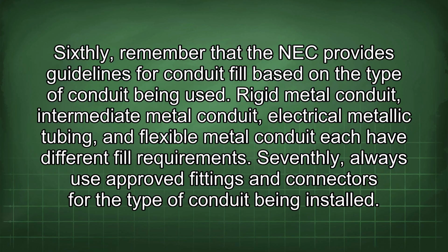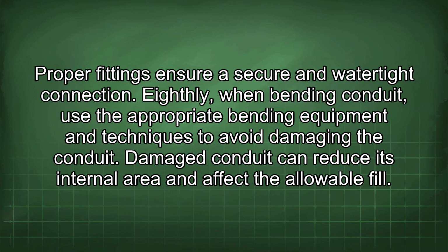Seventhly, always use approved fittings and connectors for the type of conduit being installed. Proper fittings ensure a secure and watertight connection. Eighthly, when bending conduit, use the appropriate bending equipment and techniques to avoid damaging the conduit. Damaged conduit can reduce its internal area and affect the allowable fill.